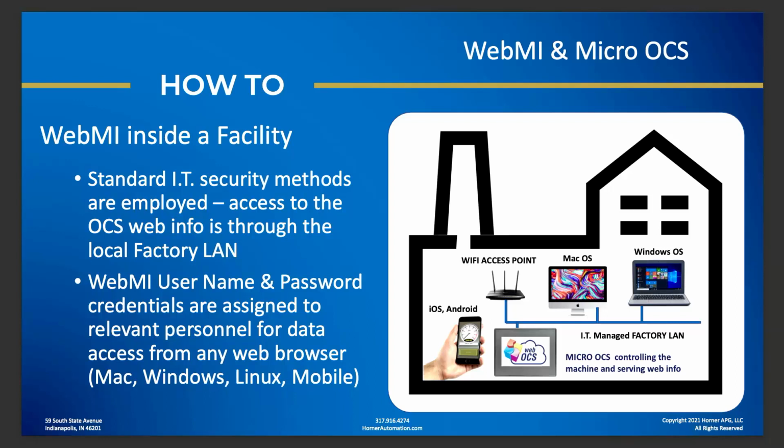Now, there is an additional step within the workflow for setting up WebMI, and that is that in addition to having access to the factory LAN, whether that's wireless or wired, the personnel that are going to be using WebMI have to have access to the piece of equipment that's being monitored. So that means in WebMI setup, there's a username and password that's required to be set up for every member that's going to be accessing that piece of equipment.